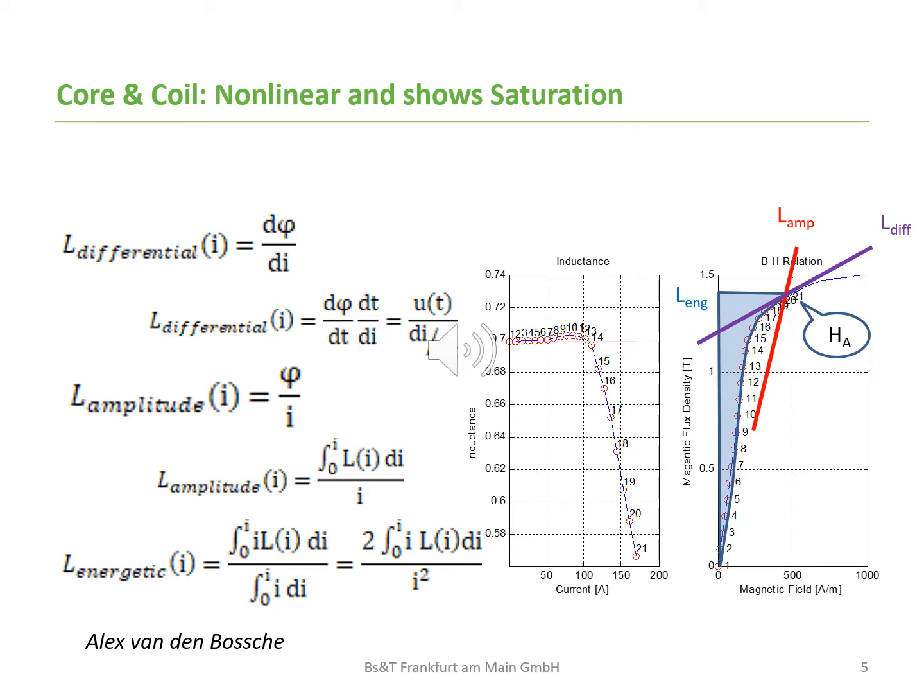Being anti-ferromagnetic materials, compared to the ferromagnetic alloys, the ferrite has lower Curie temperature and lower flux density, and therefore the loss measurement validation technique is very sensitive towards the thermal dissipation during the measuring interval.